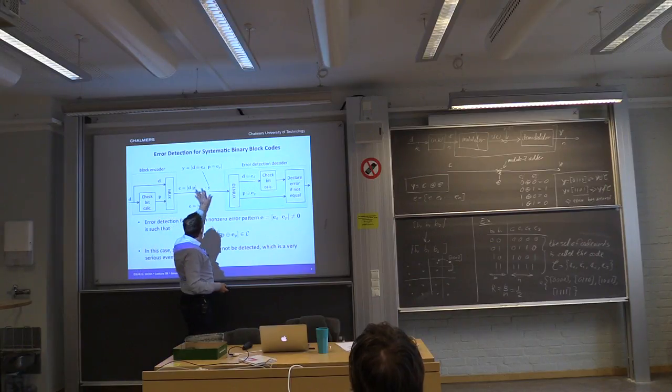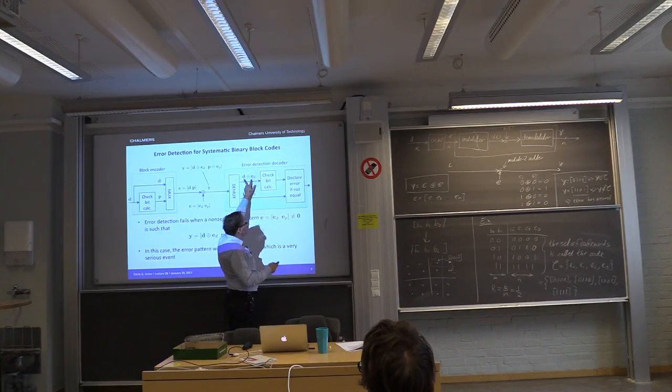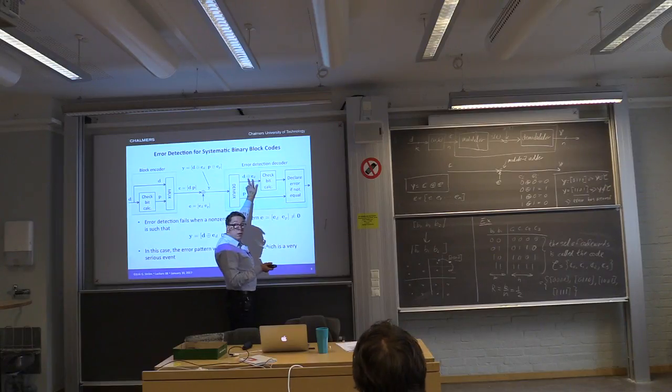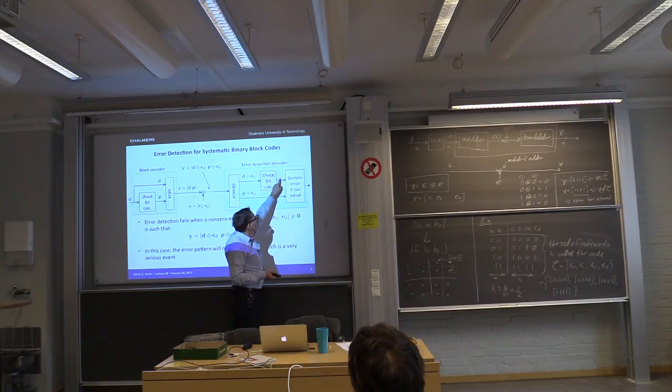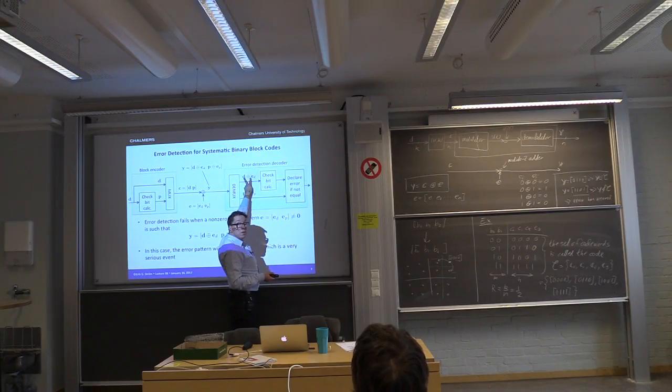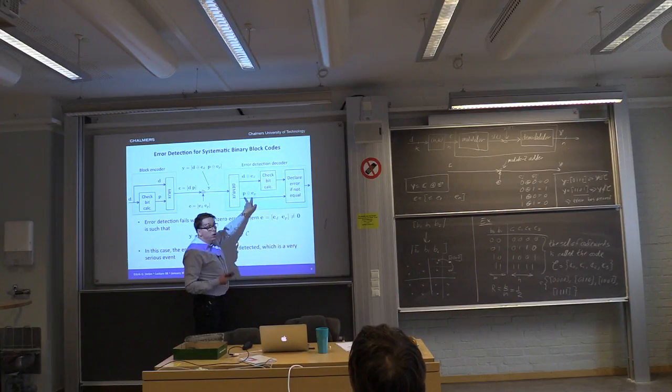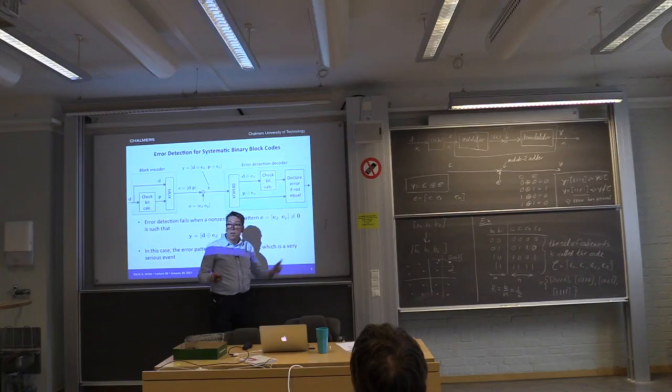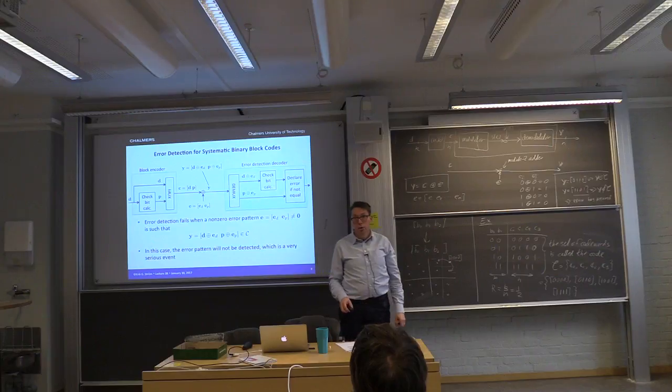So we take the data field in the received pattern, which is the data which was transmitted plus the errors, if any. Then we calculate the parity bits, which correspond to this field. And then we check whether these are actually the parity bits we received. If they are equal, we say that's fine, looks good. If they're unequal, we say error has occurred.